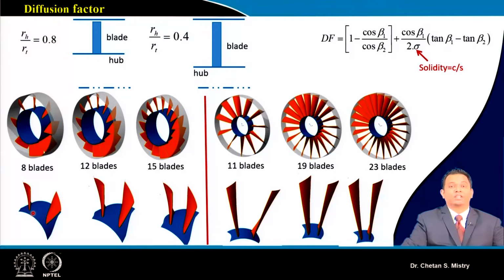Okay, so the next option is to increase the number of blades. Suppose here we are increasing our number of blades. Yes, this will give you a high pressure rise, or the pressure rise we are expecting. But because of the presence of more blades, the losses are going to increase. Those losses are frictional losses, and that will reduce your efficiency. Okay, now here in this case, suppose we have our hub to tip ratio in the range of 0.4.